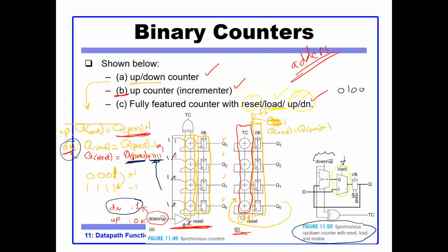Well, sometimes when you start your system and the hardware, when you power up the digital system, you want to bring up the counter to a known value, which is 000, and that's the function of the reset, which is right here. Okay, and we have another function here, which is the enable, and the enable stops counting for some reason.